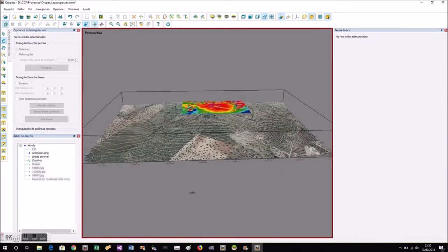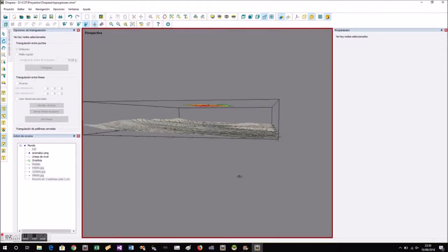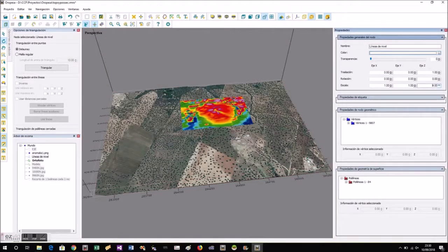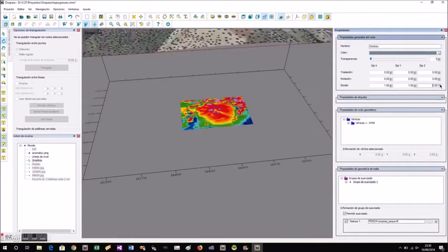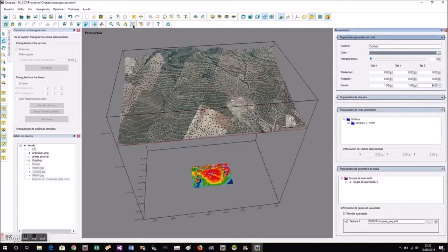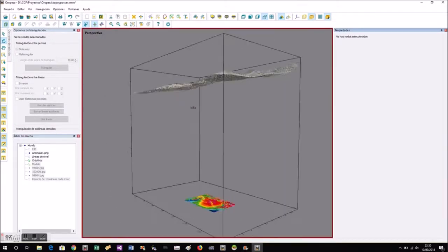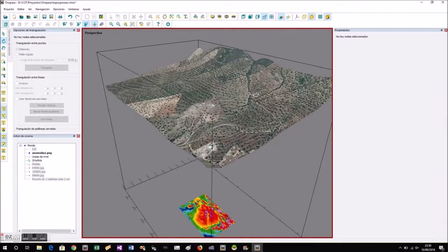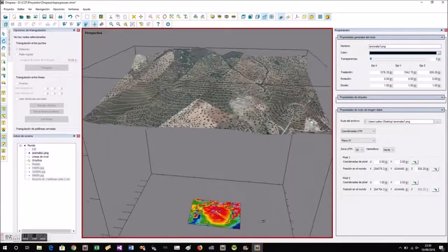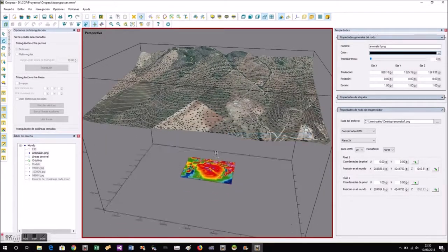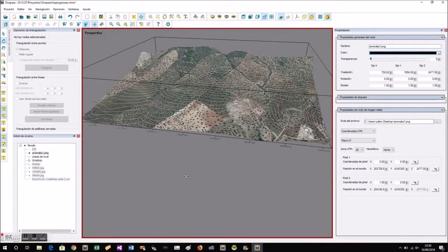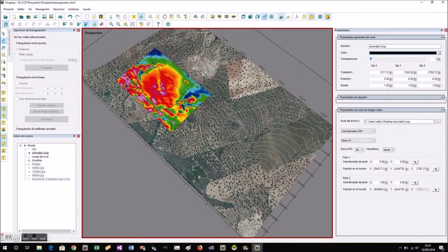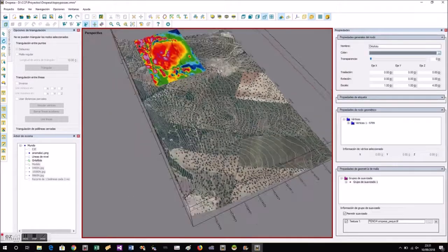It's pretty soft, you can barely see the mountains. It's very flat, right? If we want to emphasize it, we can scale the level lines, multiplying by 3 or by 4. I do the same with the triangulation, and as we see now, it looks stronger in relief. I've multiplied the z by a number, and I'm going to upload that image that I want to place in its place. I have not changed the x and y georeferencing. I'm going to assume that its position is that. I'm not going to georeference because it is an example.